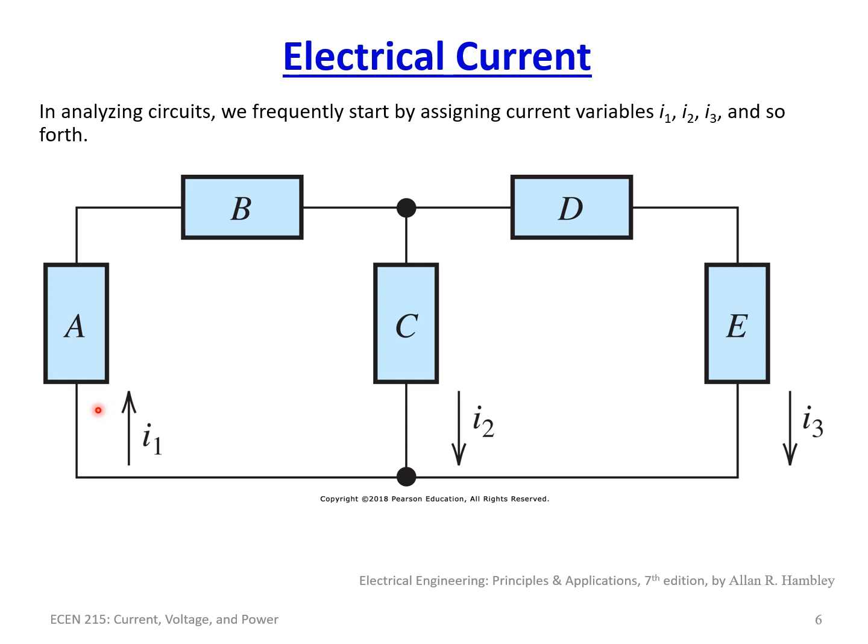So the current is going to come here, going through circuit element A, going from this side to this side is this direction of current. So if I1 was equal to 5 amps, it means 5 amps are traveling from this side to this side through A. If it was minus 5 amps, then the current actually would be going this direction, and we would just be representing it as minus 5 because we have set the direction of the arrow this way. As simple as that might sound at first, it's very important that you understand that concept.